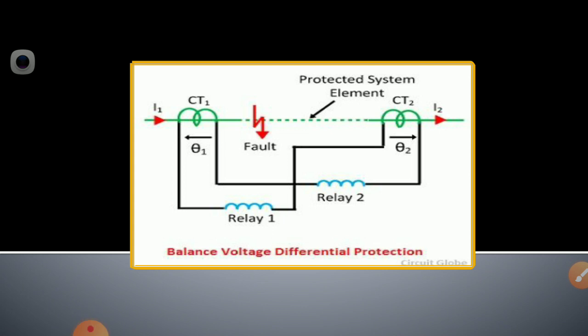the second is the voltage differential relay. So a differential relay operates upon the phasor difference of two or more similar electrical quantities. So a differential relay is the relay that operates when the phasor difference of two or more similar electrical quantities exceeds the predetermined value. In that we have got two points. First is the current differential relay, and second is the voltage differential relay.